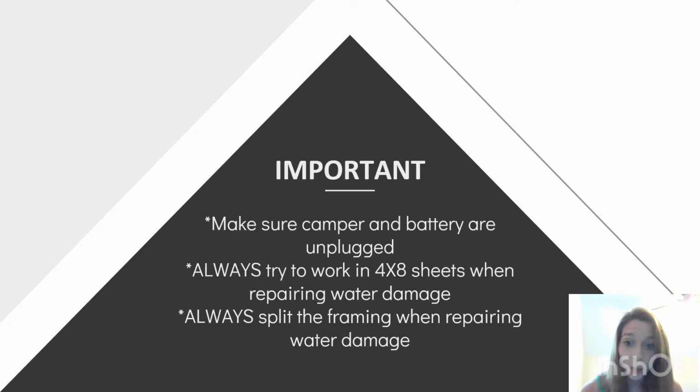Now, this is very important. If you don't listen to anything else in this entire presentation, listen to this slide. So first, you're going to make sure that your camper is unplugged and your battery is disconnected. You can even go as far as flipping your breakers off just to be safe. My reasoning for that is because you don't want to electrocute yourself, because chances are you will be dealing with electricity, your wires, all that fun stuff. So unplug your camper, don't electrocute yourself.